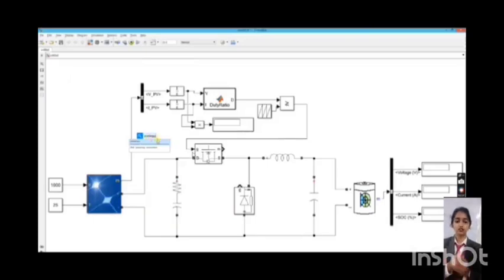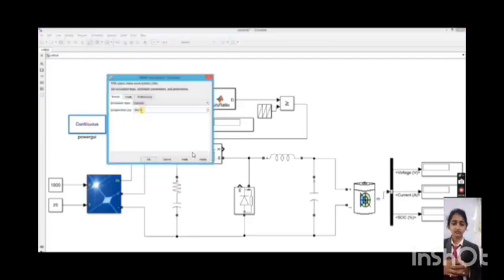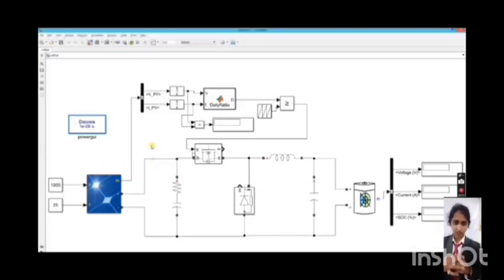The duty cycle refers to the proportion of the time that the converter switch is on, and it directly controls the output voltage of the buck converter. By varying the duty cycle based on real-time feedback from the PV array, the converter ensures that the PV panel operates at its most efficient point and the energy extracted from the panel is efficiently transferred to the battery.